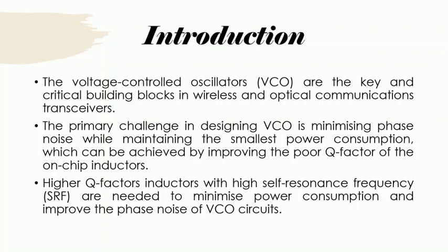The primary challenge in designing this VCO is that we need to minimize the phase noise, but at the same time maintain the smallest power consumption, which can be achieved by improving the poor Q factor of the on-chip inductors.